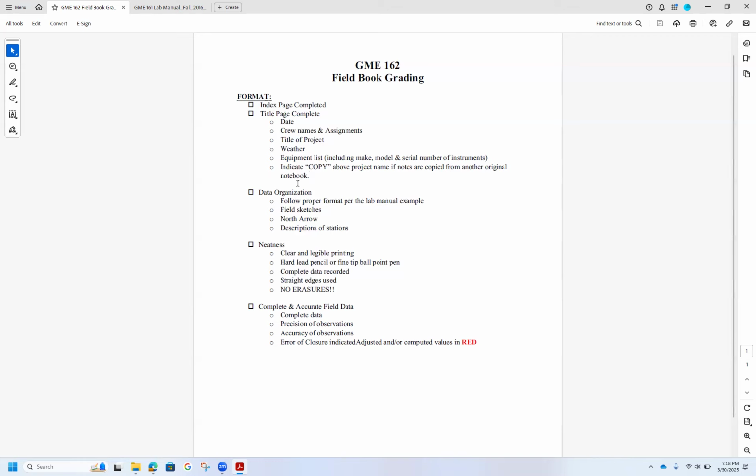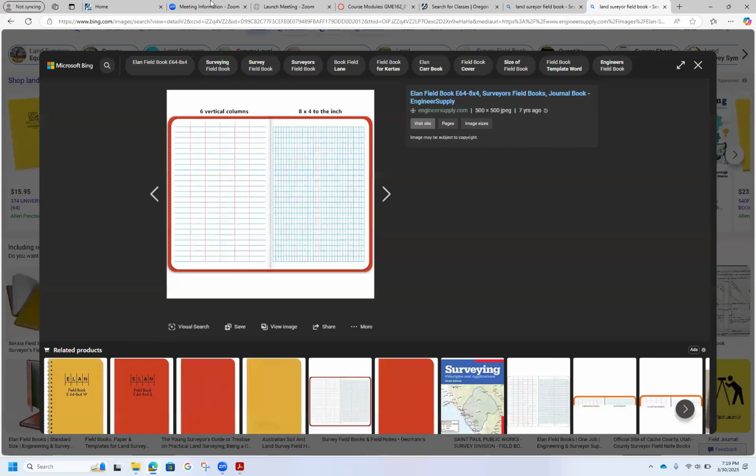No erasing. That's number one. Do not erase, because if you erase, it smudges everything. Those field books, that paper, is not meant to be erased on. It's meant to just keep the data as it's written. If you do make a mistake, let me pull up the example that I have for you guys.